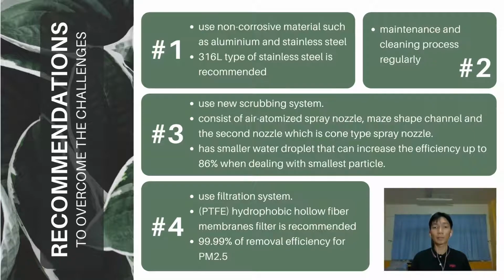Lastly, a new scrubbing system can be applied, which consists of an air atomizing spray nozzle, a mist-shaped channel, and a second nozzle, which is a cone type spray nozzle. It has smaller water droplets that can increase the efficiency up to 86% when dealing with the smallest particles.